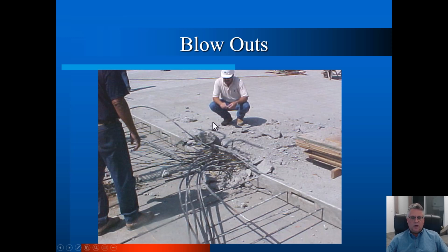The issue was that they didn't place it at the construction joint because they read the detail to say it was at the end of the building only, but the concrete doesn't know that the construction joint is not the end of the building. And when we put a tremendous amount of force there at the construction joint, it exploded in this case.